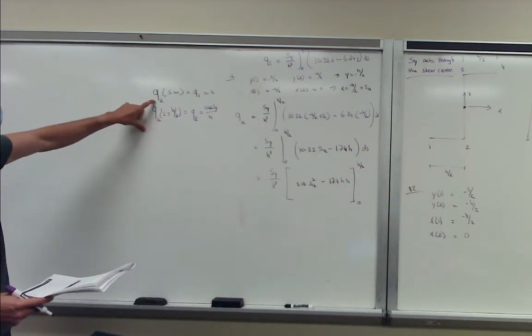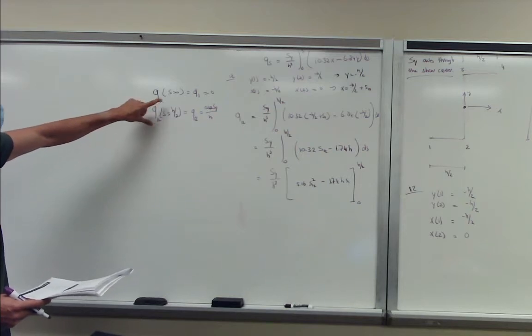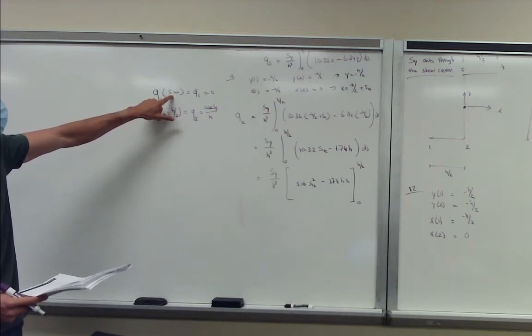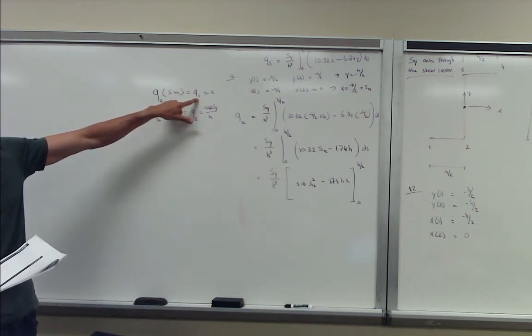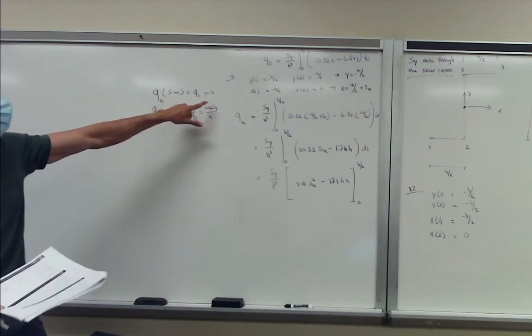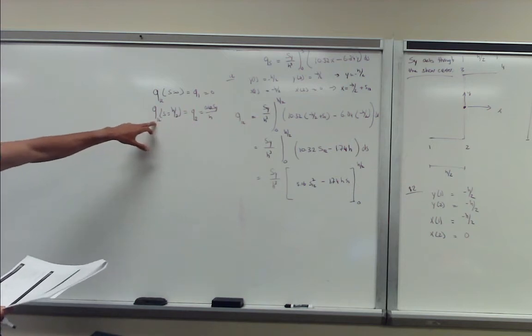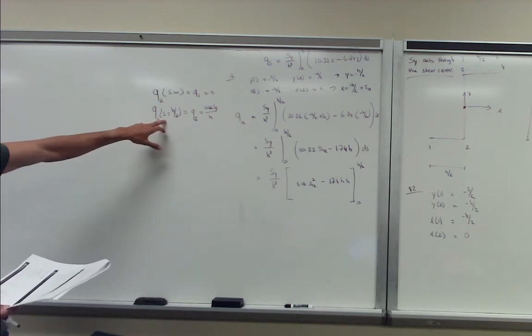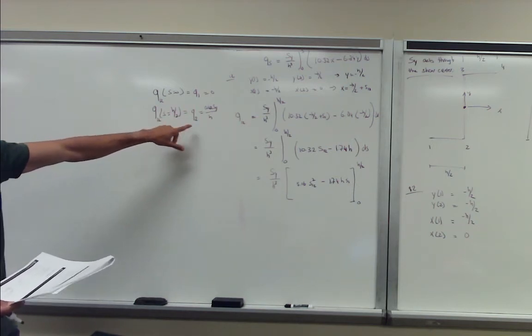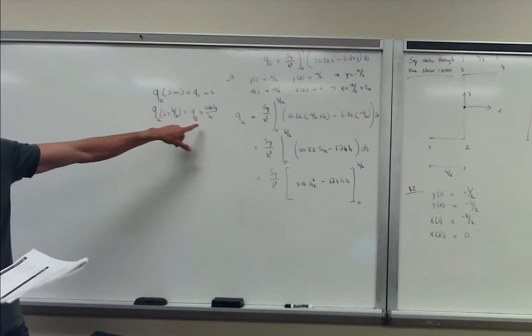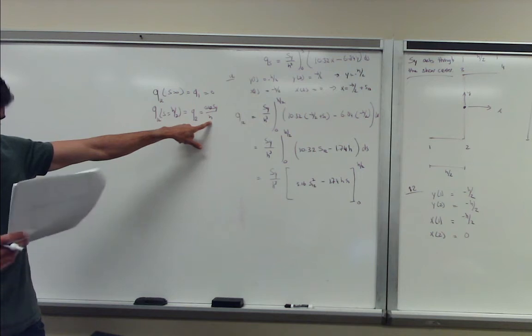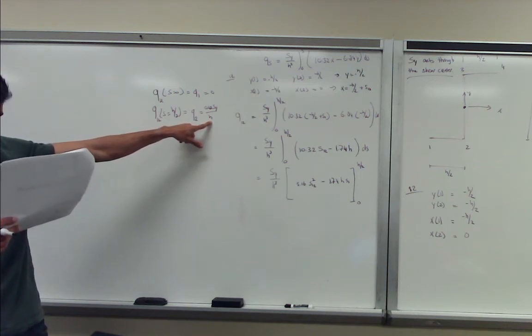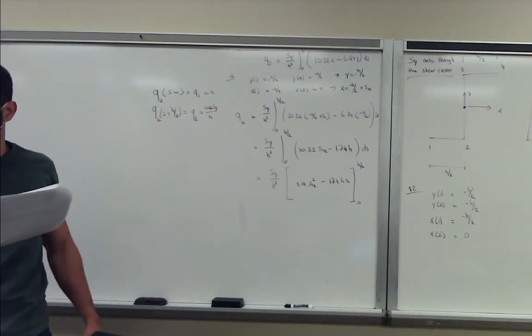So here, the shear flow of segment 1, 2 evaluated at s equal to 0 is equal to the shear flow at s1, or q1, equal to 0. Here, the shear flow in segment 1, 2 evaluated at s equal to h over 2, we call that q2, and that's equal to 0.42 sy over h. Does that make sense?